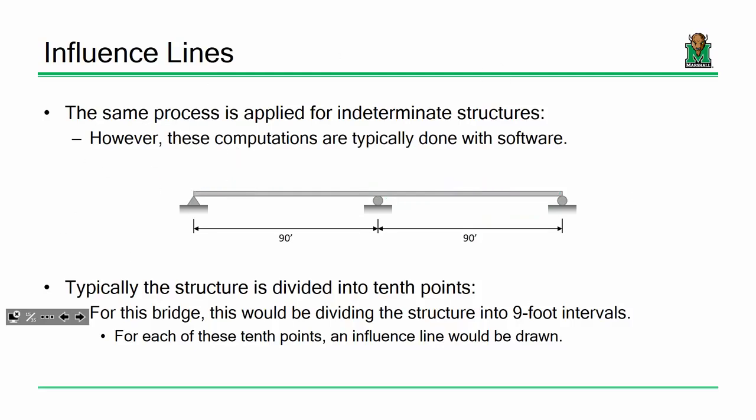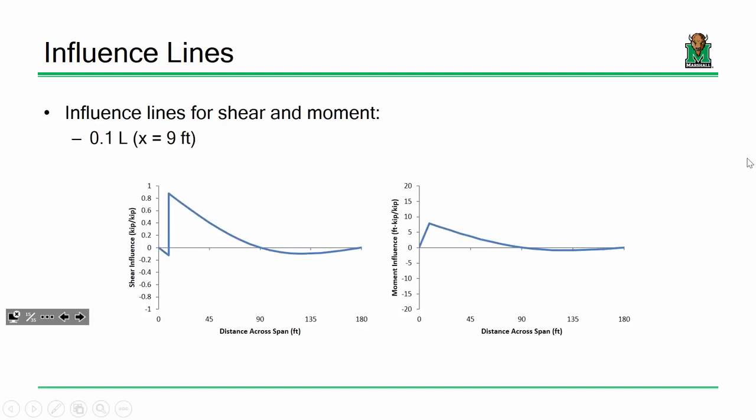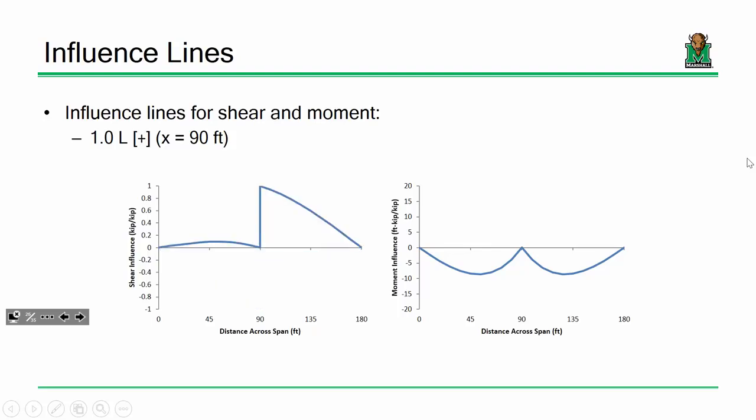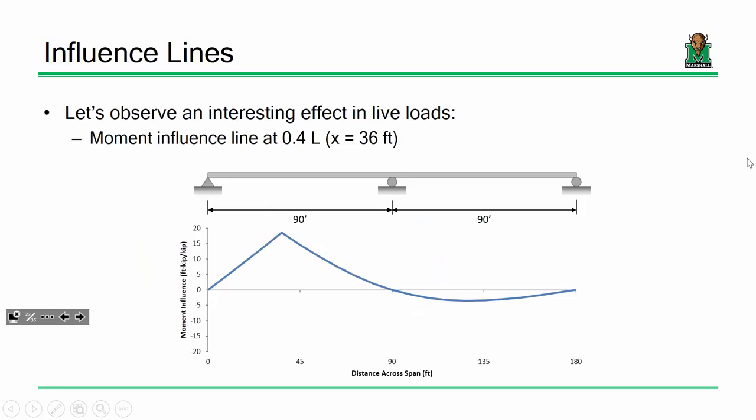Okay. So let me continue on with this, and this will make sense. Okay, so these are just what the influence lines look like as you progress. The only thing worth mentioning is that the shear diagram, depending on which way you look at it, right at the support because of the sign convention can suddenly flip over. It doesn't change your magnitudes, just your signs. It's really no big deal, not worth mentioning.